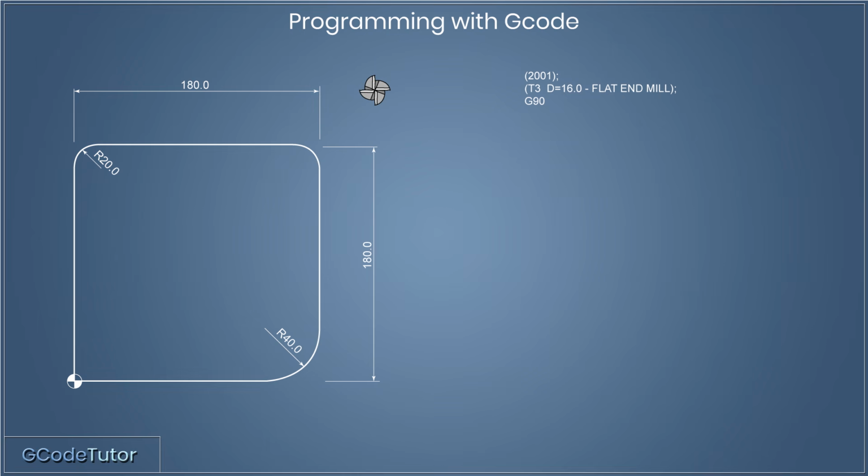The other option here is G91, which is incremental, which would run from the last known position of the cutter. So if we were moving the cutter 10 millimeters to the left, we would say x minus 10 rather than give that dimension from the datum position. So we're going to work in an absolute measuring system. Both are used quite often in programs, but I believe most CAD/CAM programs output as absolute coordinates.